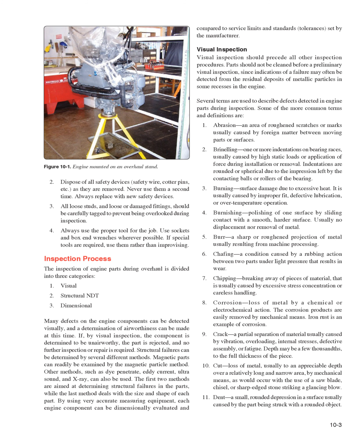Abrasion, an area of roughened scratches or marks usually caused by foreign matter between moving parts or surfaces. 2. Brineling, one or more indentations on bearing races, usually caused by high static loads or application of force during installation or removal. Indentations are rounded or spherical due to the impression left by the contacting balls or rollers of the bearing. 3. Burning, surface damage due to excessive heat.